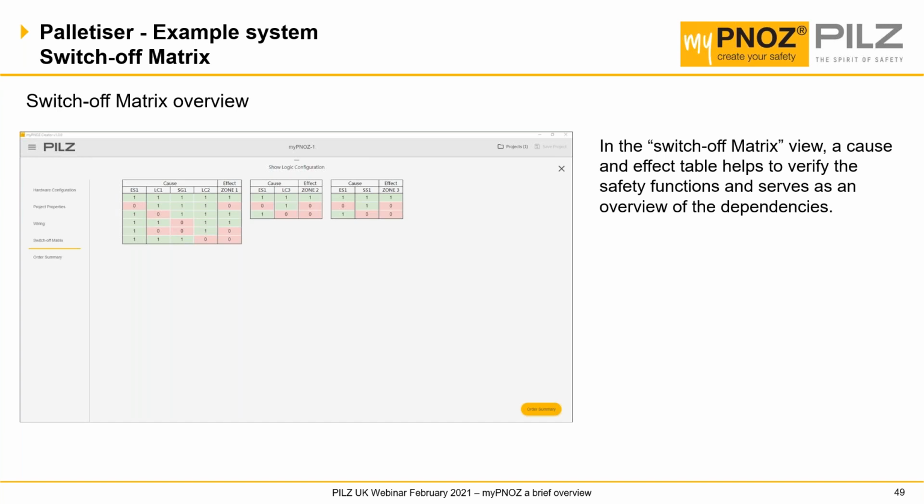There's then the OR statement. So if light curtain 1 and safety gate 1 are opposite to each other, this signal will be healthy. However, if both of them are off, the output becomes unhealthy. And finally, if light curtain 2 is broken, the output becomes unhealthy. And this is shown again on the other two slides for the other two zones.